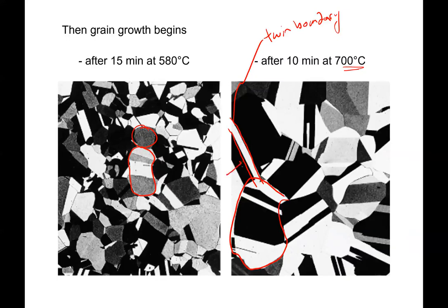Right? And so each of these is a twin. So the crystal here in the dark has twinned, and its twin area is bright because it is now angled for good reflection, and then it twins back to the original crystal direction. And that's what you're seeing through all of these, this sort of twinning and then twinning back. Okay, so all those straight lines are twins.